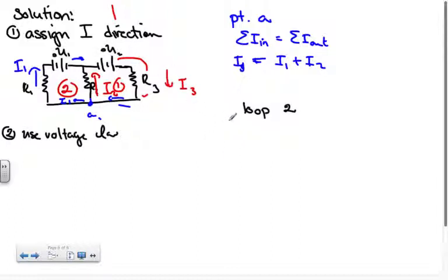So the sum of potential differences equals 0. Positive delta U2, that's what I dictated here. And this ends up being minus I3 R3. And again, I'm going with the current, so it's going to be minus I2 R2. And that all equals 0.